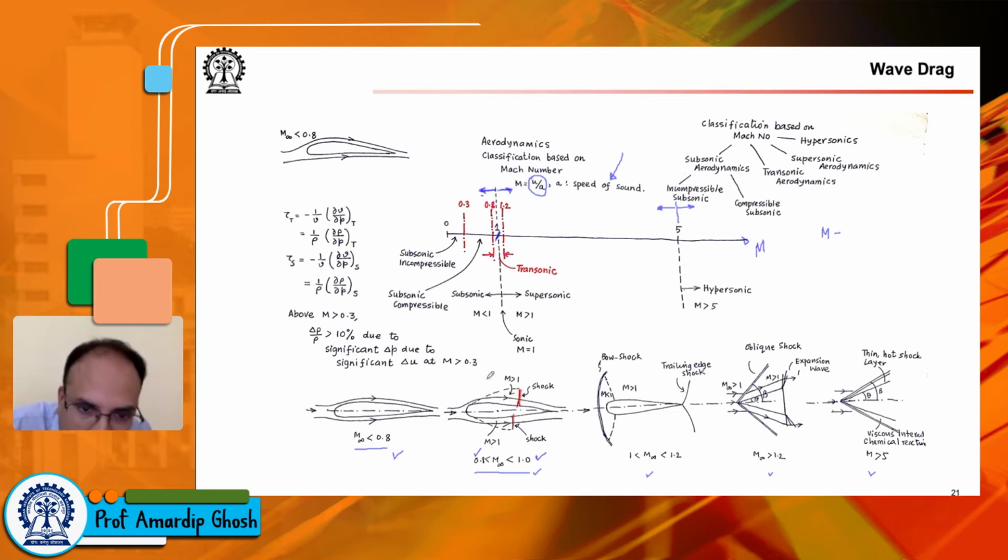So if you see this region, this dotted line is known as the sonic line. And inside this sonic line, this region is actually supersonic flow. Okay, that shaded red region is supersonic flow. So it's interesting that even though your vehicle is flying at subsonic speeds, less than 1, since it is flying close to 1, there can be local acceleration regions where the flow reaches supersonic speed.